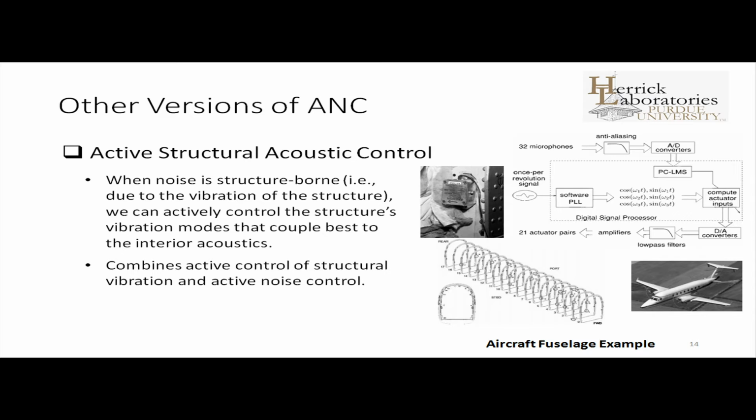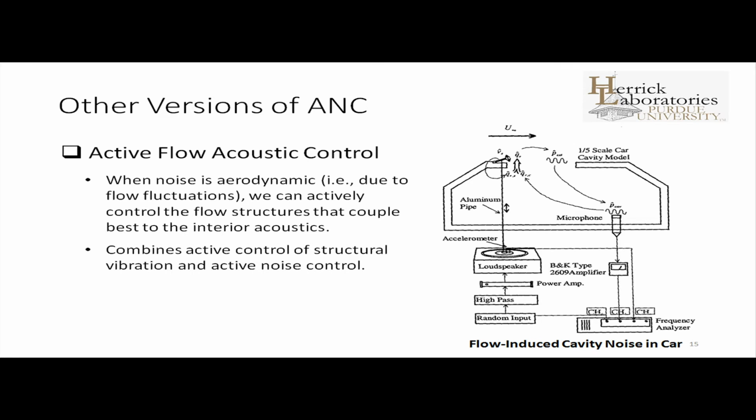And that has proven to be a little bit of a challenge, but had the kind of spin-off benefit of developing this field related to so-called acoustic radiation modes, which are orthogonal modes that allow you to identify the vibration that actually results in sound. So anyway, a bit of an editorial comment there, but it's a good thing if you can get between the source and the sound field that you're trying to control.